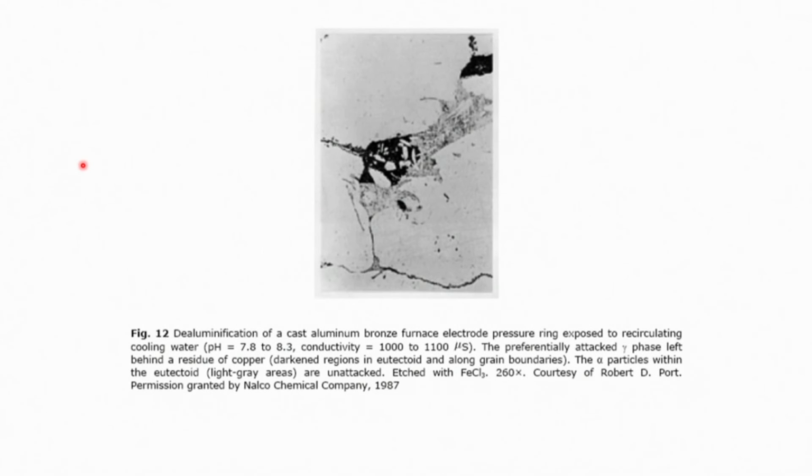So, these two kinds of corrosion are very important types of corrosion. Particularly in this talk, we discussed the two important corrosion processes: one is intergranular corrosion and the other is selective leaching. Both are observed in alloy systems, not really in pure metals. Intergranular corrosion propagates through adjacent grain boundary regions, and for it, it is very important that you find out the grain boundary microstructure prior to its application in the actual environment.